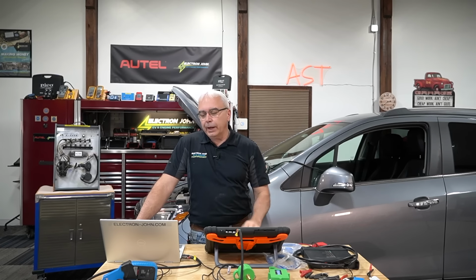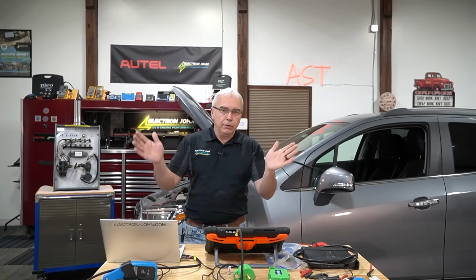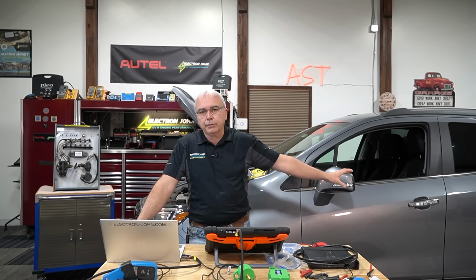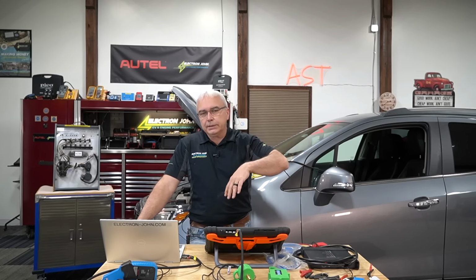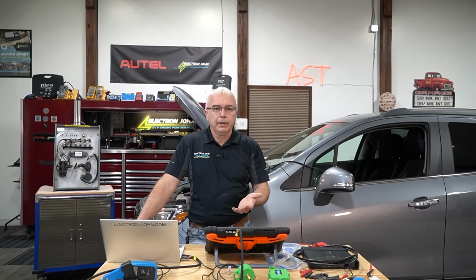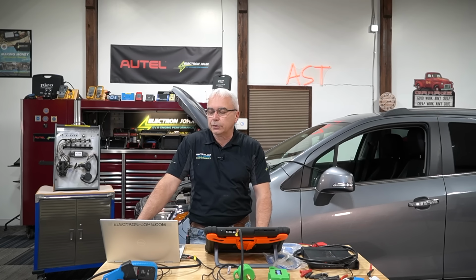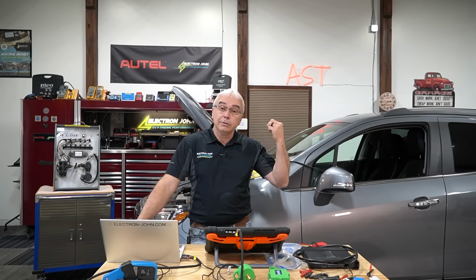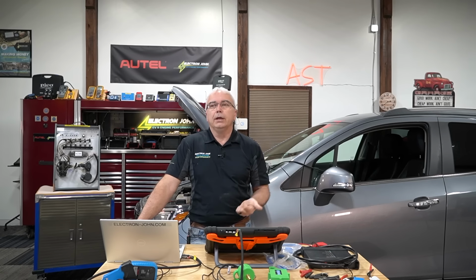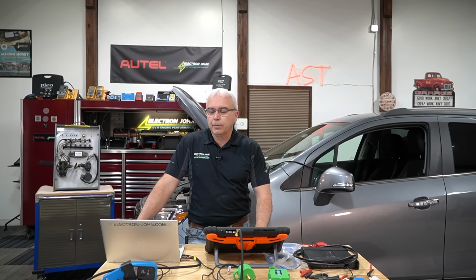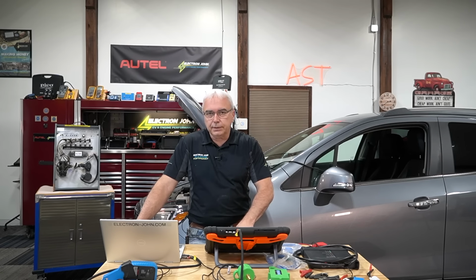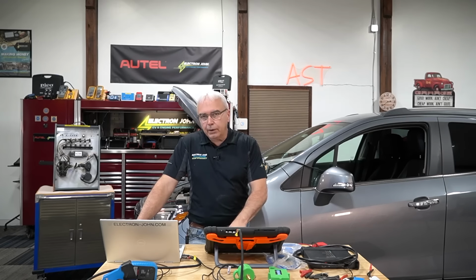So this is where my first fork in the road came. Do I want to take the dash apart to get to the radio so I can unplug the radio? Or do I want to take basically the passenger seat out, pull the carpeting back, and do the airbag module? And in my head, it was a real controversy because I was having that stereo noise, right? So I almost took the dash apart, but I said, you know, from experience, let me go after the passenger seat.